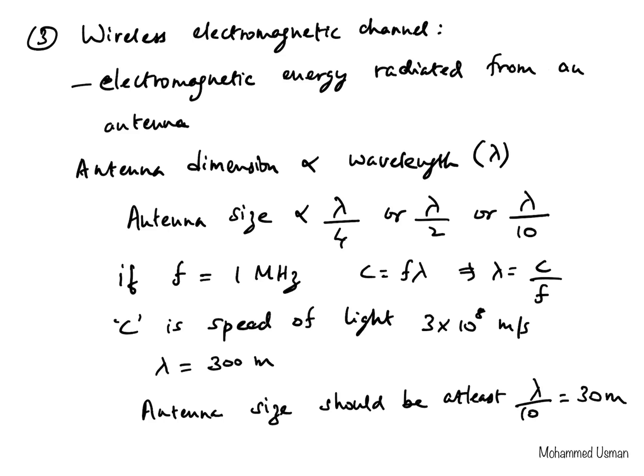So that is why typically when we are communicating for mobile wireless, the frequencies used are in the gigahertz range. In that case, the antenna size comes in the order of a few centimeters, and that allows effective radiation with smaller antennas, and incorporating the antennas on mobile handheld devices.